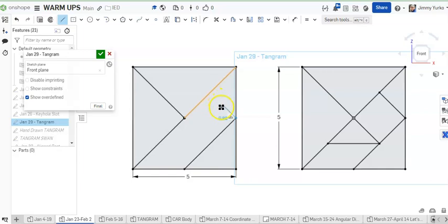If you have an occurrence like it just happened to me, where I bring the mouse back and it forms that arc, it's no big deal. That happens quite a lot, and it's actually quite useful. To get your line tool back, just bring the mouse back, release, and click and release whenever you get there. Go back to the endpoint, double click. Two clicks at the end of the line allows me to exit.